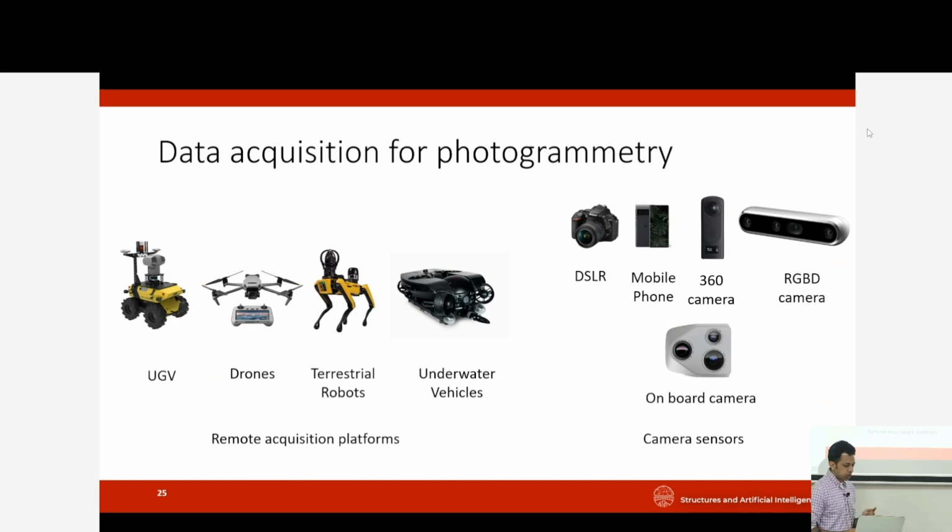There are also other challenges with photogrammetry that are separate from the ground control points, because we're doing a bundle adjustment and we're simultaneously determining the camera positions and the 3D points. That nonlinear optimization may result in some drifting of estimates, and that may warp your whole scene.